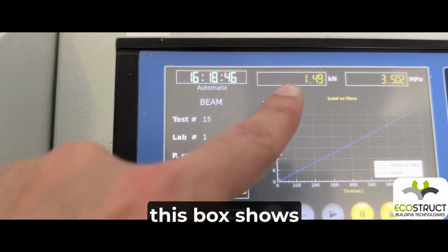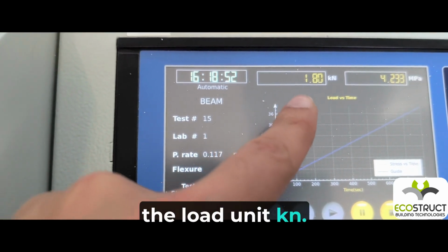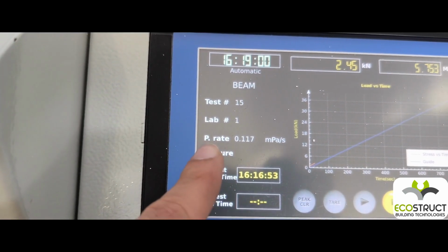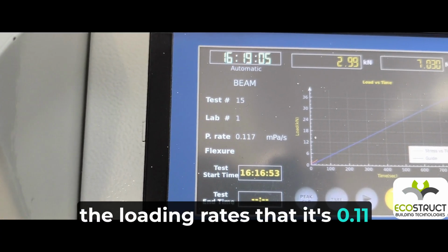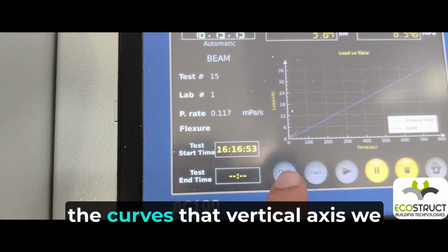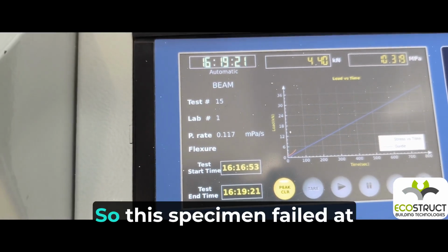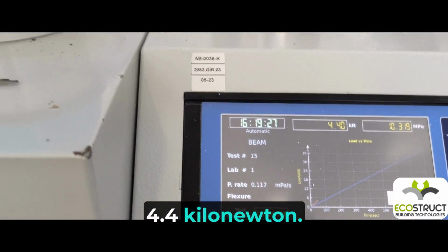As you can see, this box shows the load, unit kilonewton, and this box shows the calculated stress. And here we have the loading rate, which is 0.11 megapascal per second. And here we have the curves, where on the vertical axis we have load and on the horizontal axis we have time with the unit of seconds. So this specimen failed at 4.4 kilonewton.